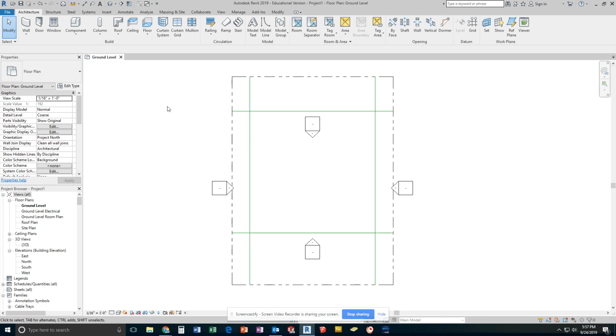I would suggest saving this as your house project, because in several of your drawings, your boundary line will need to be visible. You will likely remove these lines later after you've drawn your exterior walls, but this will help to make sure all of your setbacks are correct.